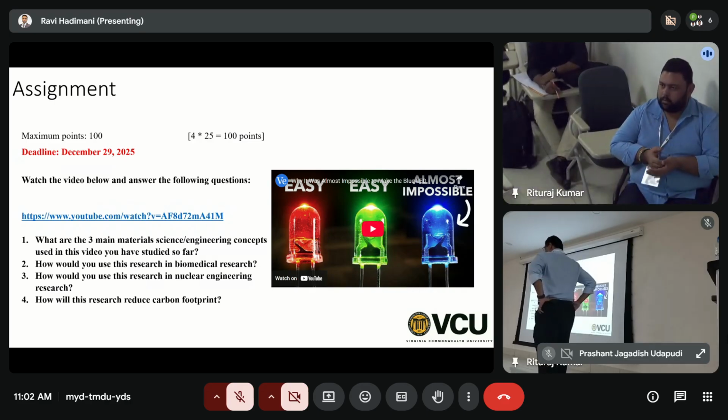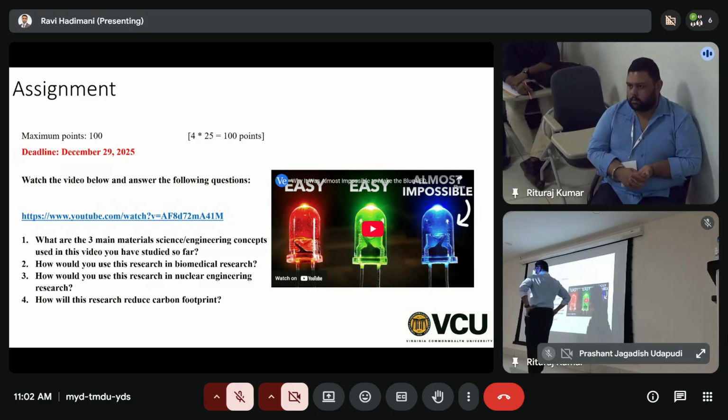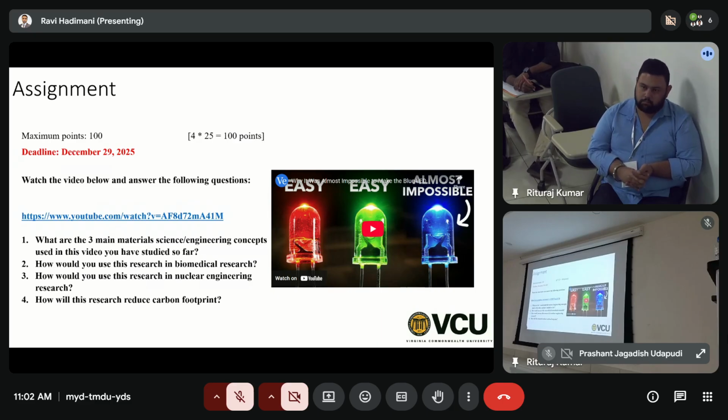Okay, so the substrate, right? There are two requirements. One is the substrate itself. What kind of substrate? That's the first slide I showed, atomic radii. You have to match the atomic radii of the substrate with the atomic radii of the material that you are depositing. If there is a mismatch, then you have internal stresses that will change the property of the deposited film.